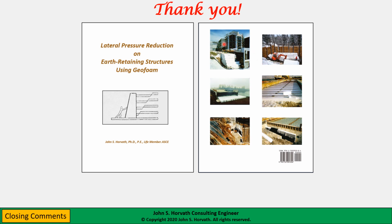This was a very early project here in the United States that used EPS block geofoam to reduce lateral pressures on a below-grade parking garage. As I pointed out during the presentation today, in those early projects, people did not realize they needed to stair-step the EPS blocks into the retained soil.